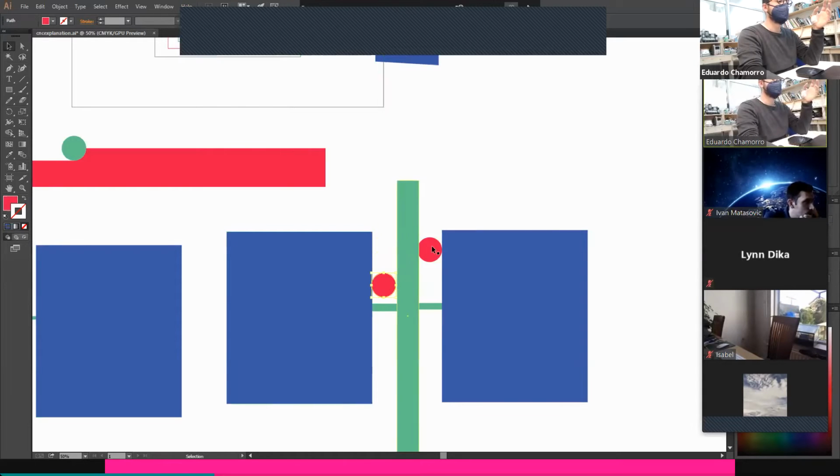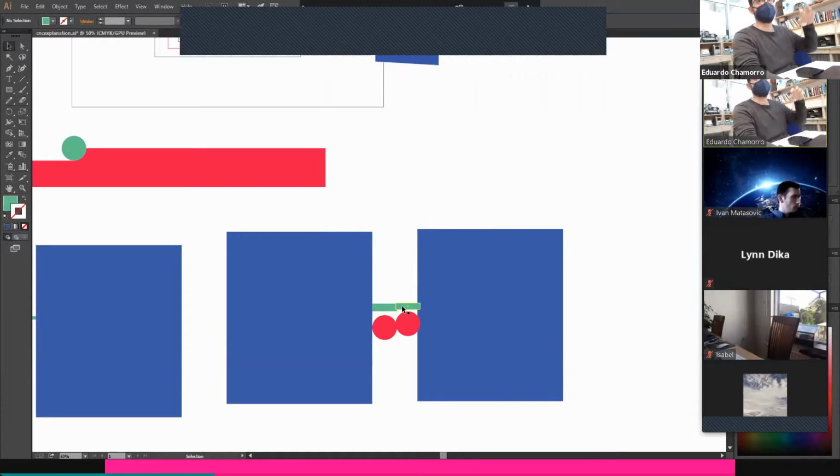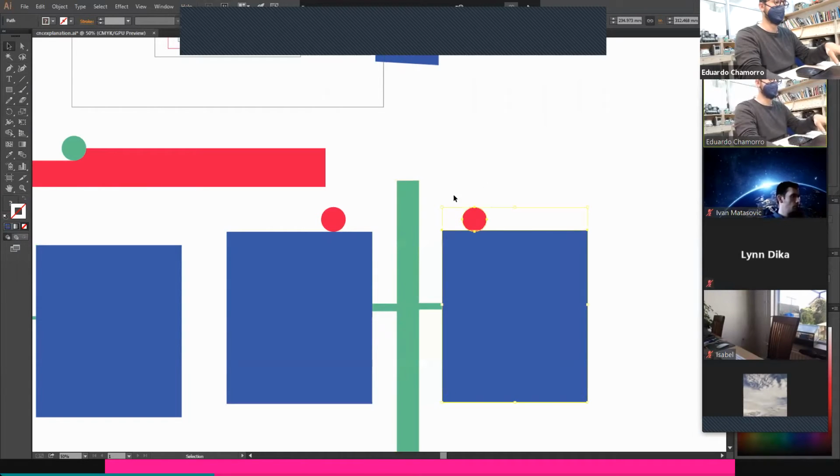But if you don't leave enough space between these two cuts, say we have cut this part and we have cut this part, if these two parts were close enough, we will not have this material. That means your tab is going nowhere, attaching maybe, if you have luck, to another tab. So you always need to leave enough material so the tab can attach to a leftover piece of material that is not going to be cut by something else. It's quite important.